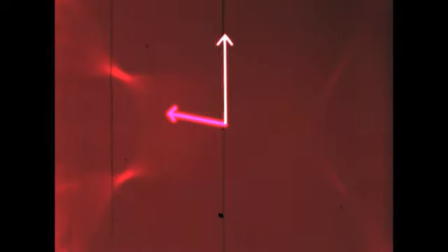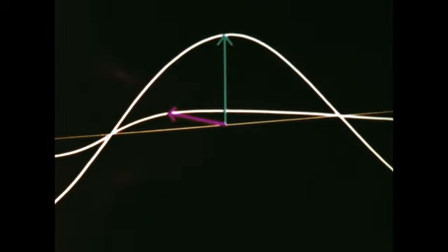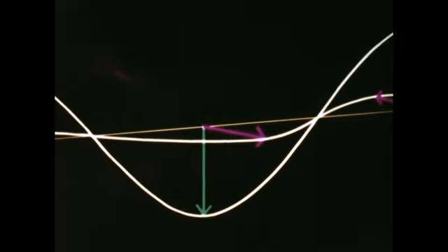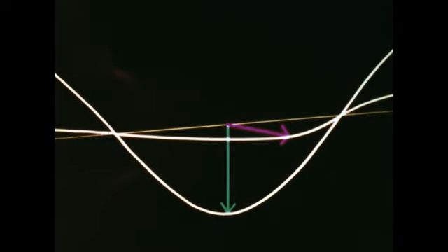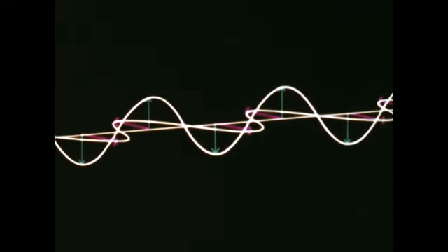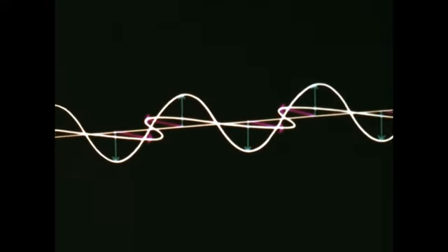Vectorially, these lines represent the peaks of the radiating waves. Notice that their direction reverses at the next half cycle. Since the peaks of these two waves occur simultaneously, they are in time phase. The traveling waves are therefore said to be in time phase and space quadrature. The polarity of an antenna is determined by the plane of the E field. To obtain a maximum signal, both the transmitting and receiving antennas must be in the plane of the E field.